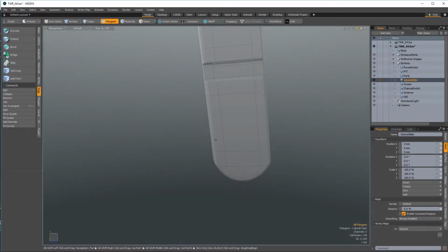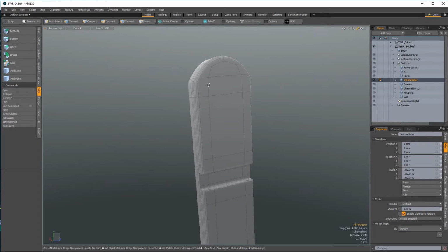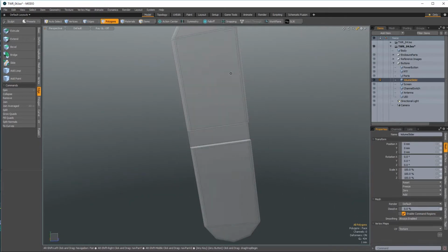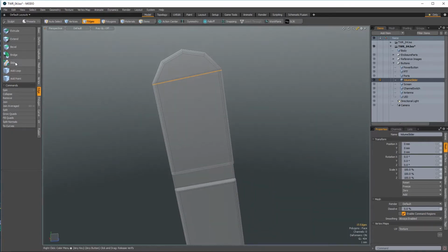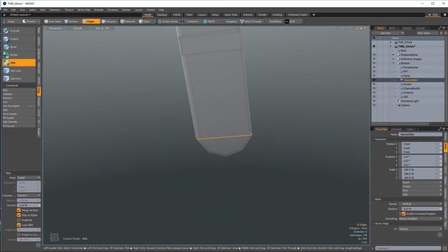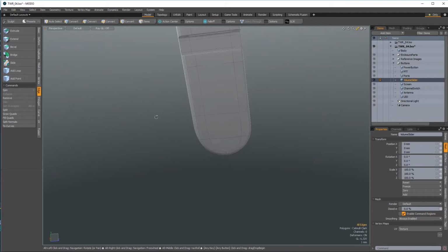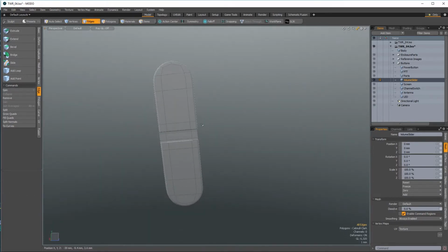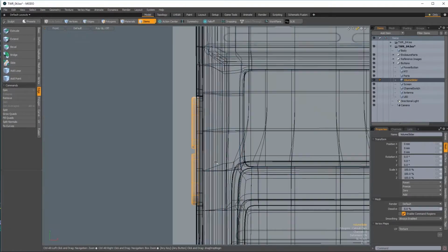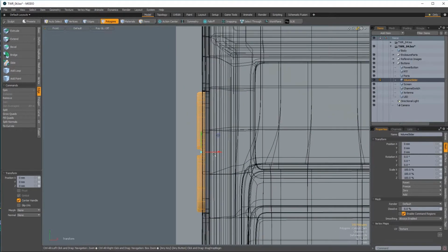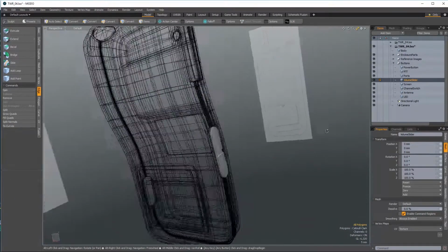Okay, you can see the round at the top and the bottom of our volume slider isn't looking so round. We have these little kinks on either side, and that's because this supporting edge is way too close to these edges. So let's slide this edge down to give it some room, and we'll slide this edge up. Shift Tab. There, that looks a lot better. And let's bring back our enclosure, unhide with U. And let's look at this placement from the front. I think that's a little too far out. So let's move this in like so. And I think that looks fine.